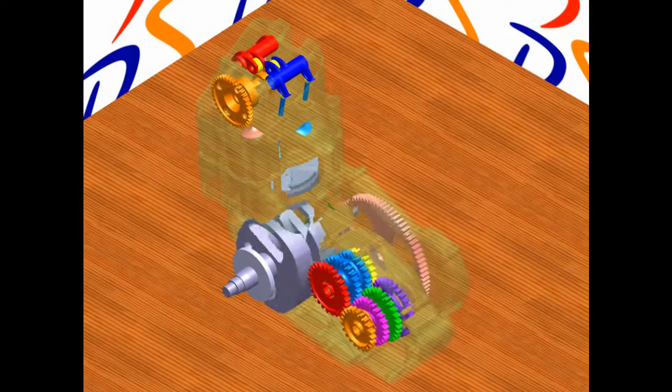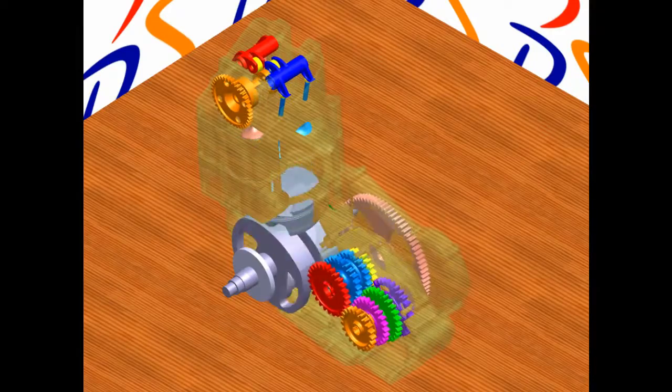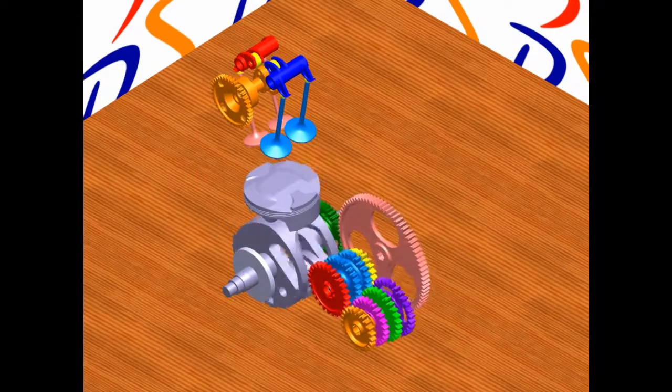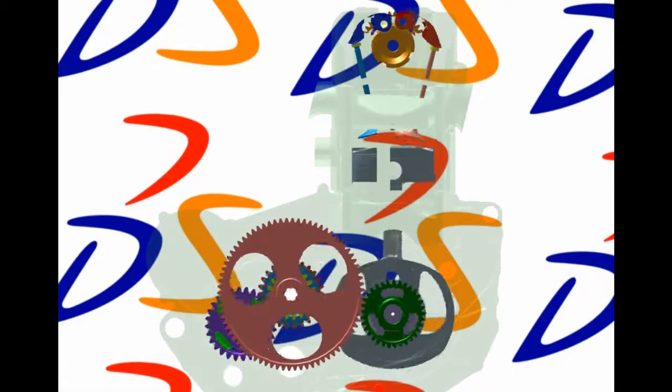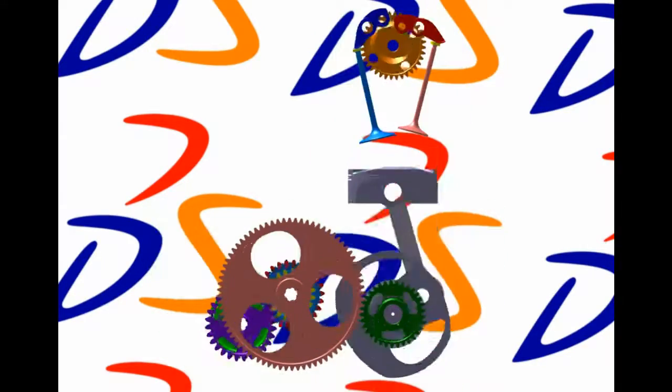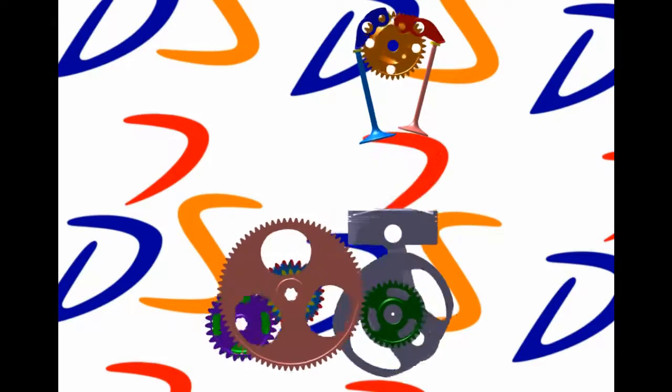For this kinematic assembly, the driver is the crankshaft using the angular command. Focusing on the engine side, the crankshaft drives the conrod big end through a revolute, and same again to the small end attached to the piston. The piston is on a planar joint to restrict the degrees of freedom to a single linear motion, replicating the cylinder bore.